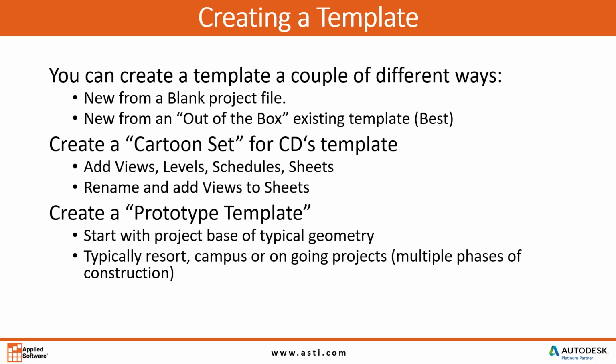Sometimes with prototypical work, you can also create a template that has geometry in it. So if you have an existing building, and you're going to have phases of this building where you're adding on to it, with renovations and additions in a phased approach through that construction, you can maybe create a template that has base geometry in it as well. So there's a couple of different options for creating templates, and it can get pretty complicated.